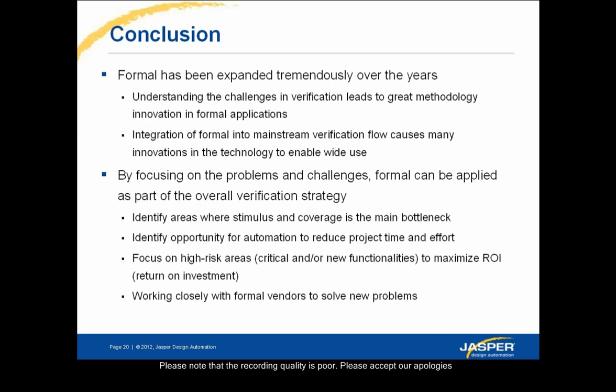It's just, yes, you exercise it, but that doesn't mean you've verified it. And that's absolutely right. Code coverage is a pretty bogus metric as a proxy for simulation quality. But people have become comfortable with how to use it and with experience. And so we're looking at how you apply those same sort of techniques of coverage, cones of influence, constraints versus assertions in the formal space.